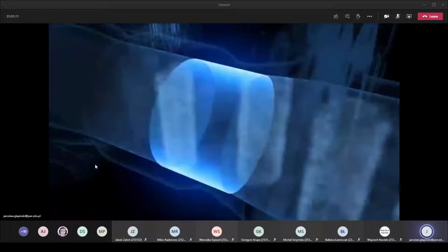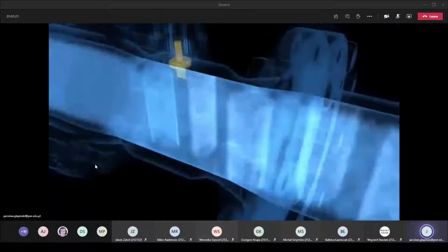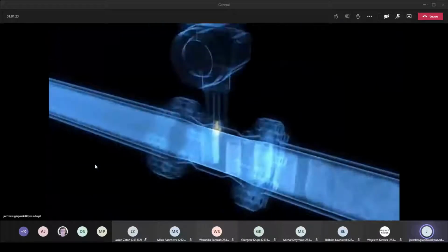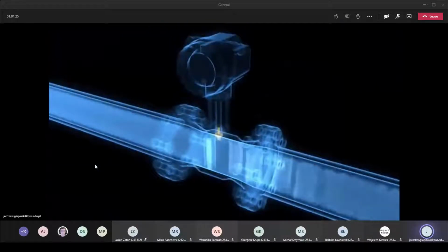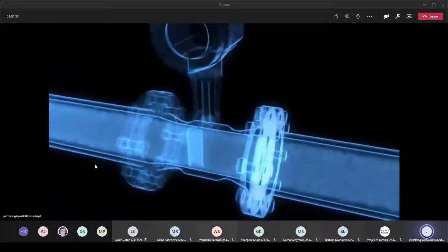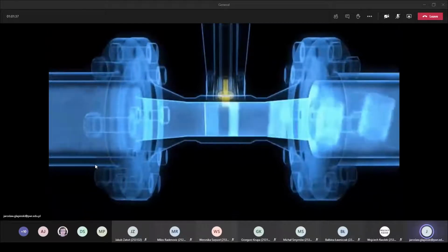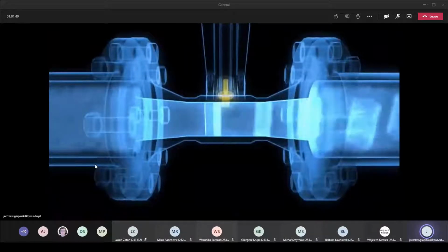The distance between two consecutive vortices corresponds to a defined volume of fluid. Therefore, total flow can be calculated by counting the vortices that pass. The higher the flow velocity, the higher the measured frequency of vortices. In some applications, the velocity is too low for perceptible vortices to form. However, the velocity can be increased simply by installing a vortex meter that has a reduced cross-section. This modification does not affect the measuring accuracy.